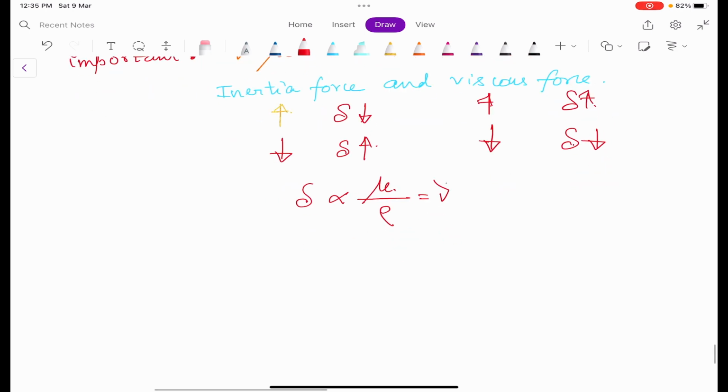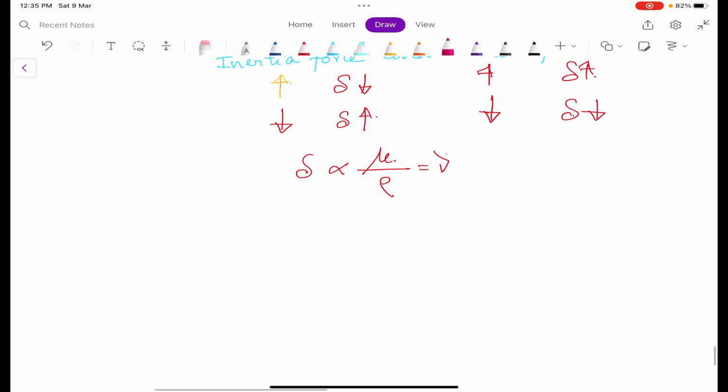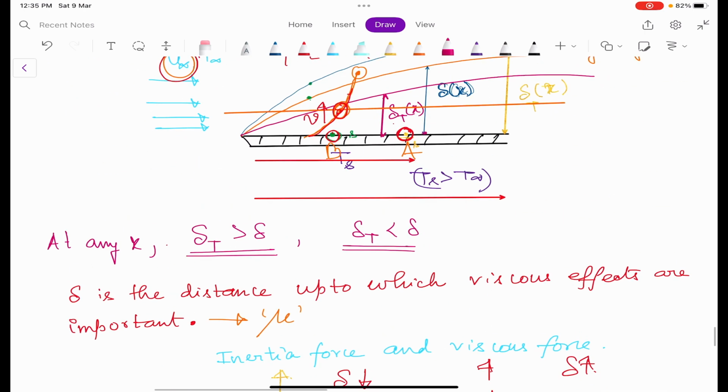Similarly, now if we talk about the delta T, so delta T is thermal boundary layer. So we know some property that is called K, thermal conductivity. So K of fluid. Now if K is more, now we are having this T greater than T infinity, then by conduction the heat should flow in this direction from the plate to the fluid, right?